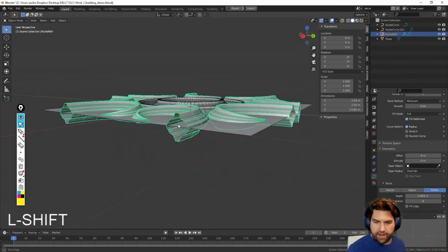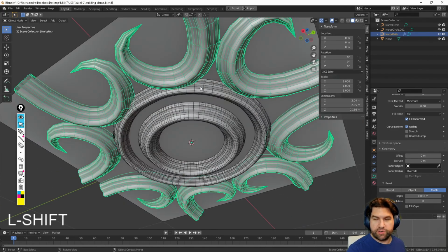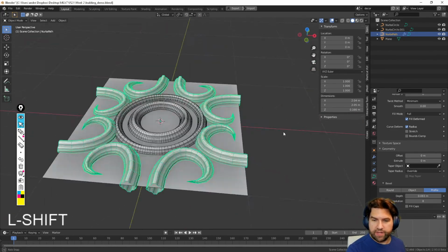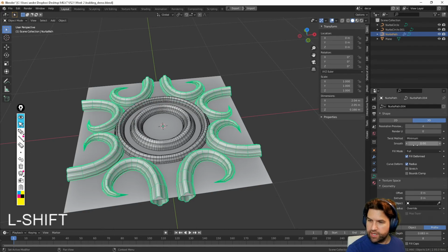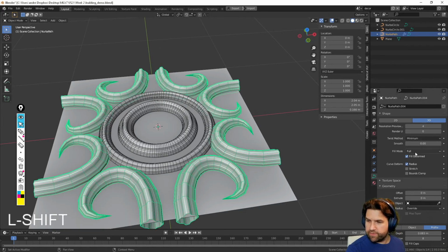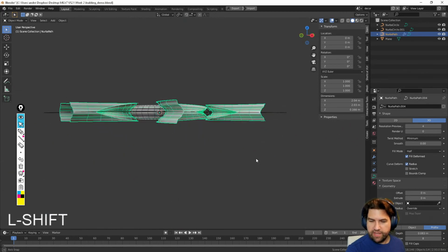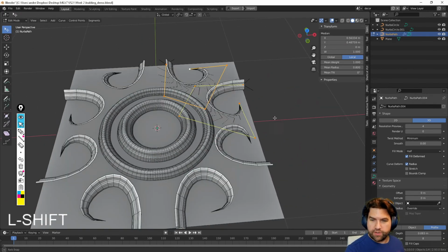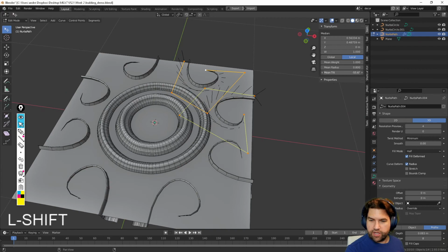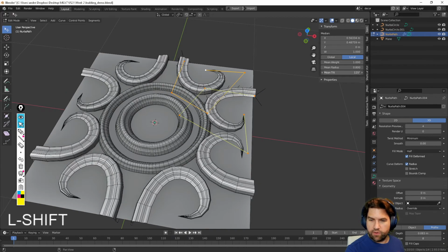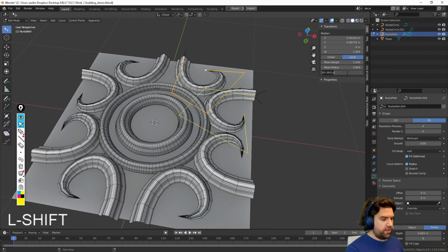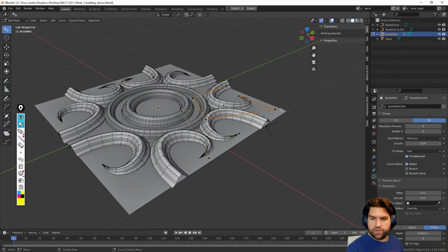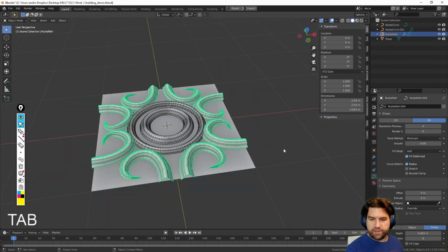And another problem I have is all the geometry is going through it. I only want the top bits. It's actually not that hard to change. Up in my settings here, I can swap it from full to half. And we can see we only get half of it, but it's not the half we want. But of course, as you recall, all we got to do is change the tilt of the whole object together. So it's going to be, in this case, 90 degrees for the whole thing. And now I don't have a bottom to it.